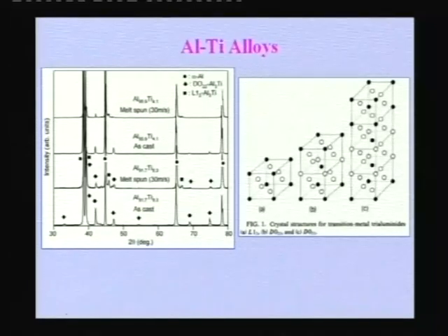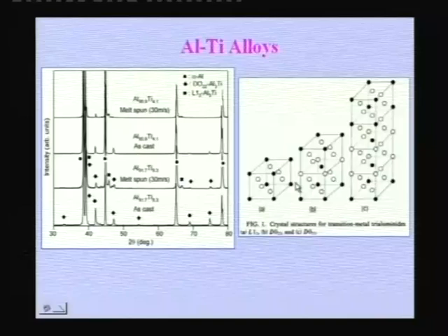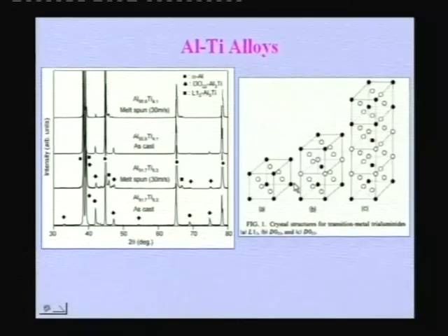either ferrite or austenite or carbides. All kinds of stabilizers we know, and we know that if you add certain alloying elements which have similar crystal structure to that of the parent phase, there is a possibility of that particular structure being stabilized. So if you want austenite to be stabilized, you add some FCC elements. If you want ferrite to be stabilized, you add some BCC elements. Similarly, in these intermetallic compounds, elements such as chromium, manganese, copper, and nickel are known to stabilize the L12 structure. So people try to add these elements to see if they can be stabilized.